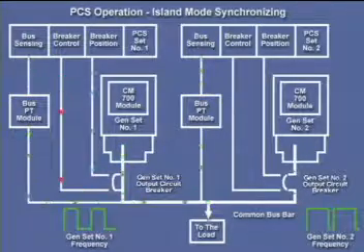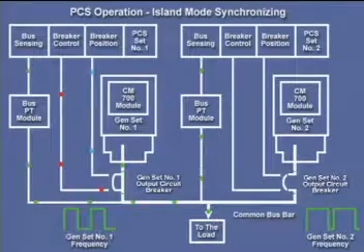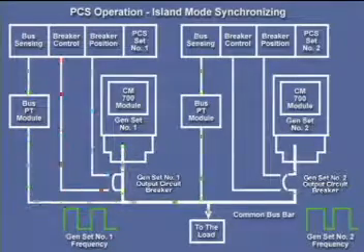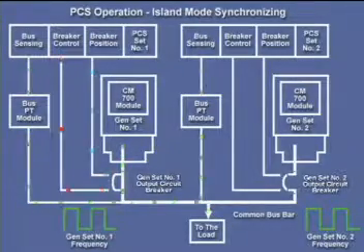In automatic mode, the integrated synchronizer in PCS signals the CM700 to vary genset frequency from -10 to +10% of nominal using the speed bias signal. This brings the generator and bus into phase. PCS also matches the genset voltage to the bus, and when the PCS has established synchronization, it sends out the circuit breaker close signal.